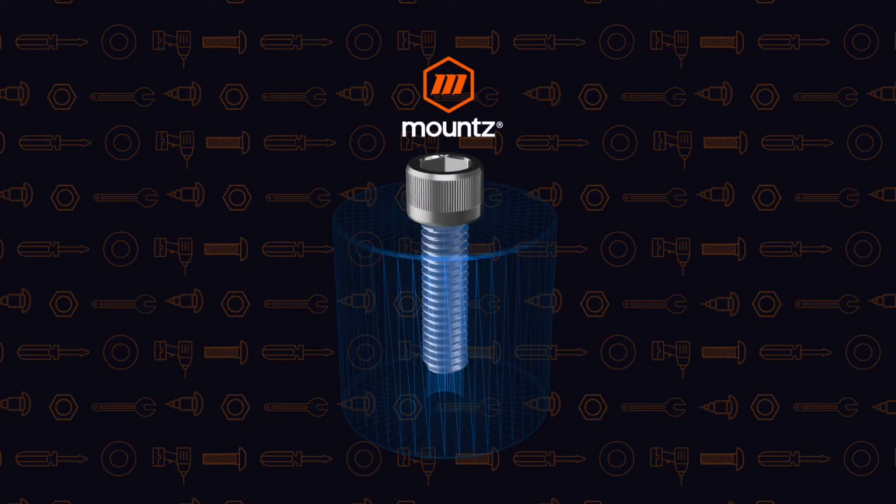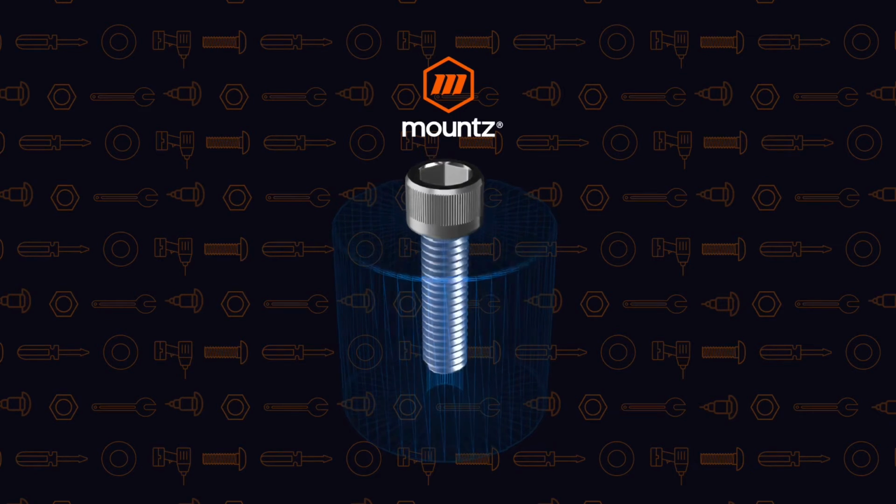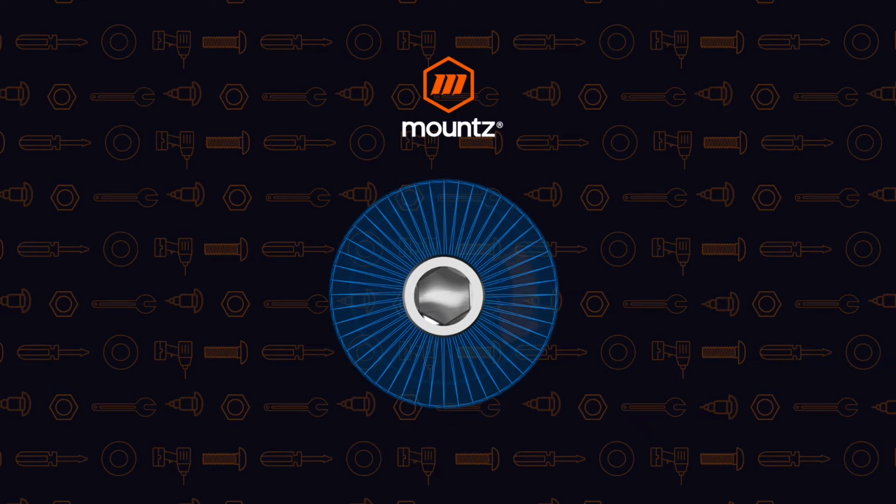So let's go ahead and we can look at a couple different animations that will display what we're looking at. And so in this case, in the first movement test, we are just turning the fastener in the tightening direction just a few degrees to see what the torque value is that we are seeing. And that's going to be very close to the value that it was originally torqued at.